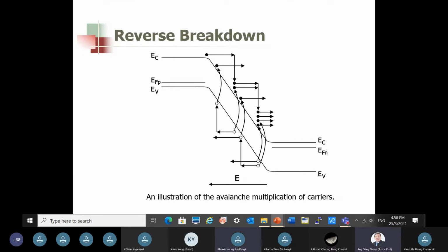All right. Now, to understand this, you need to realize that the movement of holes can be interpreted as the opposite movement of the valence band electrons. You are right, a hole is actually an empty energy state. Strictly speaking, it doesn't move. However, its movement can be visualized to be equivalent to the opposite movement of the valence band electron.